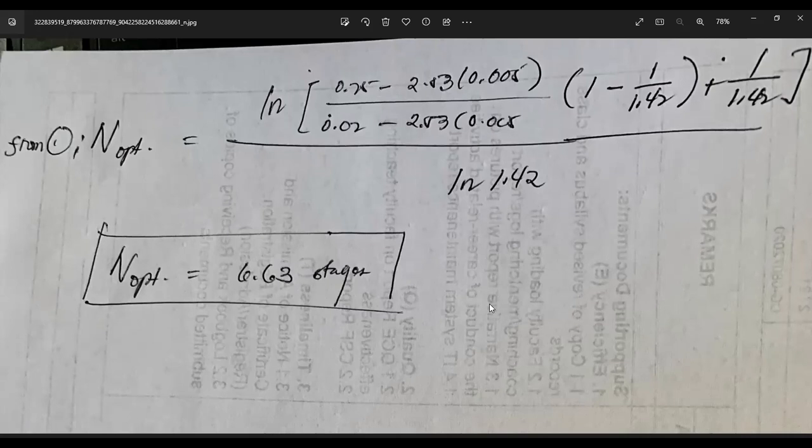Okay, because this one simply determines the stages, what's the minimum solvent requirement, or some problems would even ask for what is the recovery, percentage recovery. And speaking of percentage recovery, you just simply account for the amount of solute that goes with your solvent. So in this case, if it's gas absorption, the amount of solute in the L1. So that amount divided by the original amount in the feed, that would be your percentage recovery. So how much of the solute present in the feed was recovered in your process.